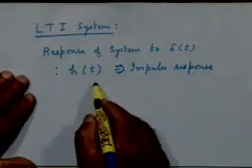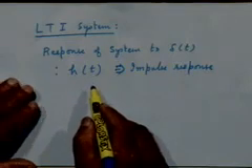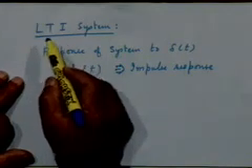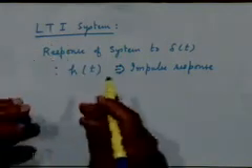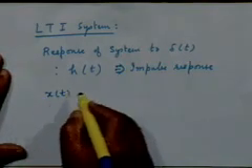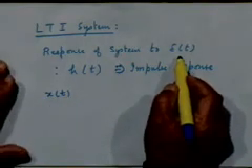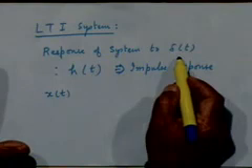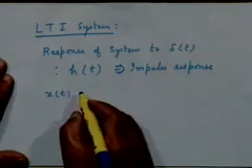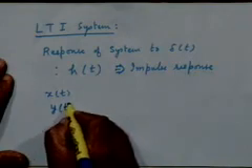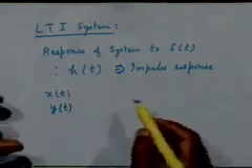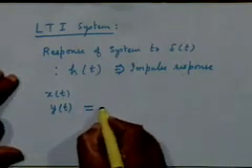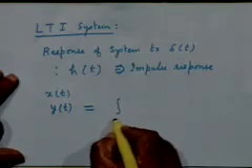The significance of the impulse response of the system is that, in view of the linearity of the LTI system, and in view of the fact that any signal x(t) can be expressed as a superimposition of suitably scaled and suitably time displaced impulse functions, it is possible to express the output y(t) in terms of a linear combination of the responses to these impulses. This is best expressed through the convolution relation between the input and the output.